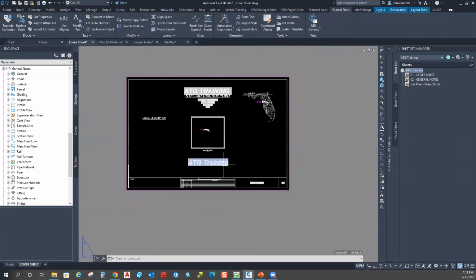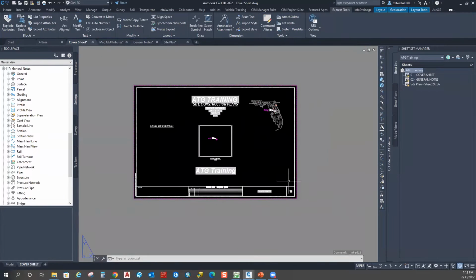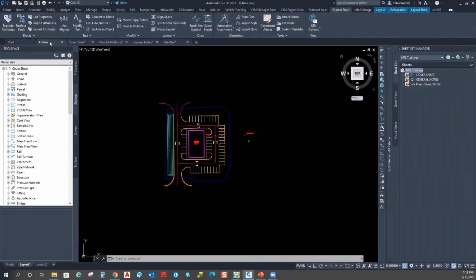So this is a very fast way to start to annotate your drawings using all the field data through your sheet set. As you start to build the sheet, you're not constantly having to put all this data in: the name of the project, the street, the client name, the revisions, the renumbering. All that data could be pushed through the sheet set. And that's another way to automate some of that annotation in AutoCAD. All right, let's talk about some other ways. Let's talk about tool palettes.